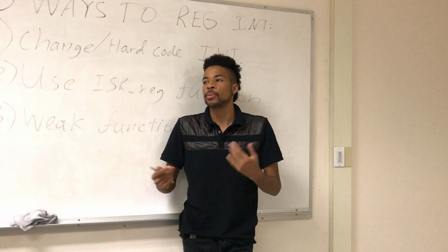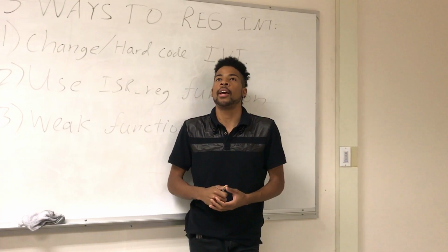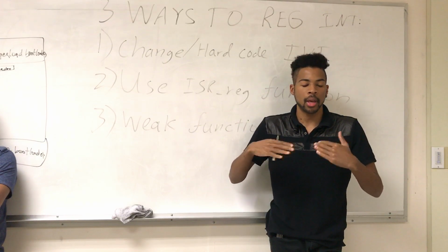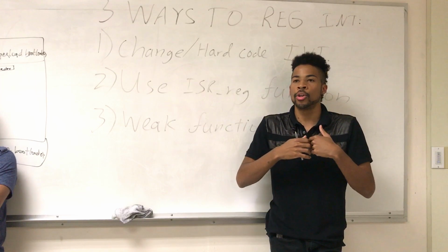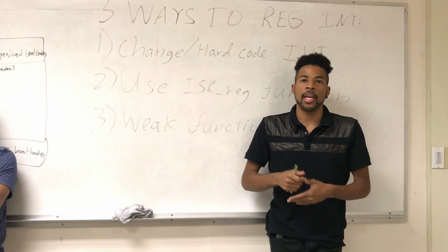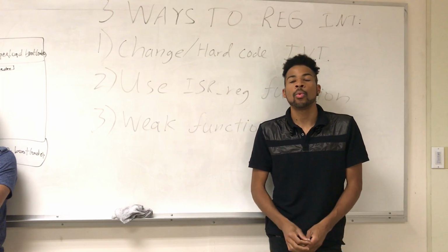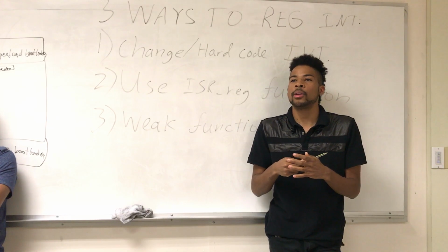So basically, when an interrupt occurs, run your callback, but try not to put any printfs or polling. Don't try to poll in it. If your interrupt runs for too long, and another interrupt comes in as well, you can end up with your code crashing. So we want your interrupts to be as concise and as small as possible. Are there any questions about the lab?